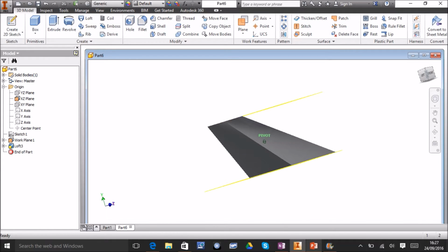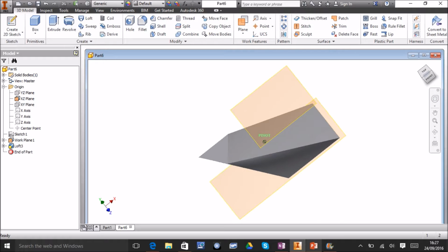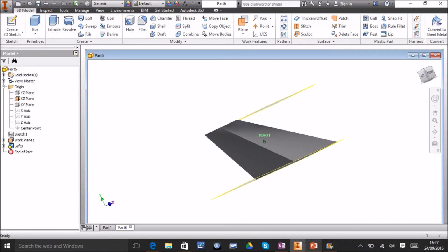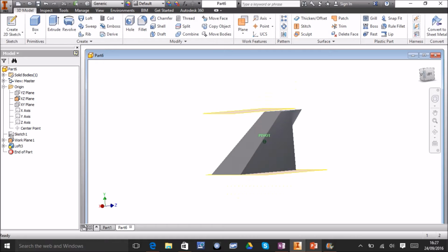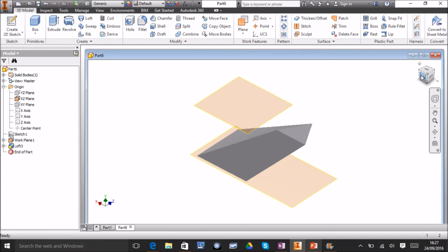And what we've ended up with, because of the particular quirk of going from 4 sides to 3 sides in our loft, we've got this little deformity. So sometimes you have to be quite careful with a lofted profile and check that it actually makes sense. In this case, it doesn't quite, and it hasn't quite worked, but it does get across the idea that your lofts don't have to be directly above each other.